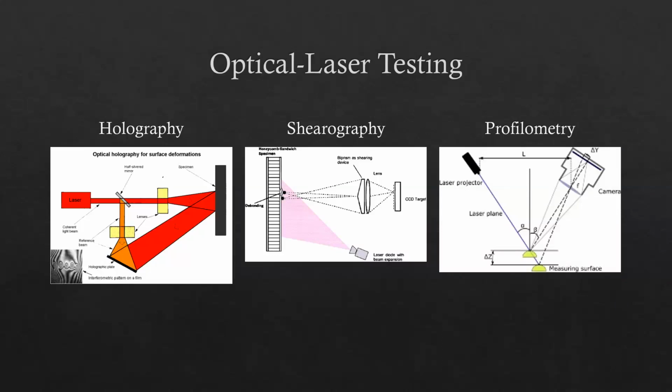We used profilometry for dent mapping on our airplanes, and it could do dent mapping of the skin, like when a plane flew through hail or something like that. It sped that process up by orders of magnitude, where before we had to manually map each dent. Profilometry could map an entire area all at once and send that data to the manufacturer to get approval to fly the plane after it got turned into a golf ball.